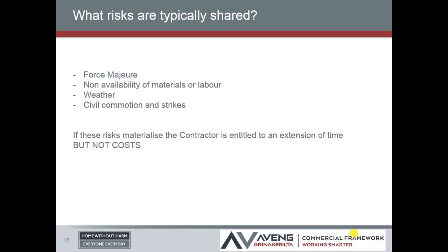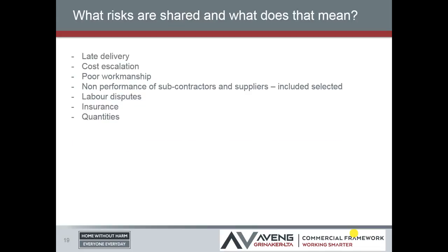And the final one is civil commotion strikes, and you've got to be very careful here. If it's a site-specific strike over something like pay or terms and conditions, that generally will not entitle you to an extension of time because it's something that you can manage. It's a commercial thing that you have to manage. Whereas if it's an industry-wide strike, or if you're on a site with multiple parties and there's a site-wide strike, like we currently, as this is being recorded, are on Eskom site at Kusile and Medupi, rather than your own specific labour, then you can get an extension of time but no costs. So it's really important that you understand where these sit.